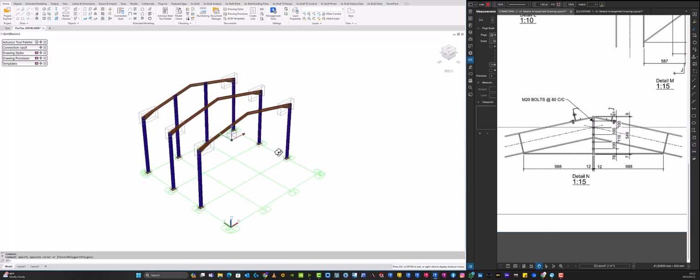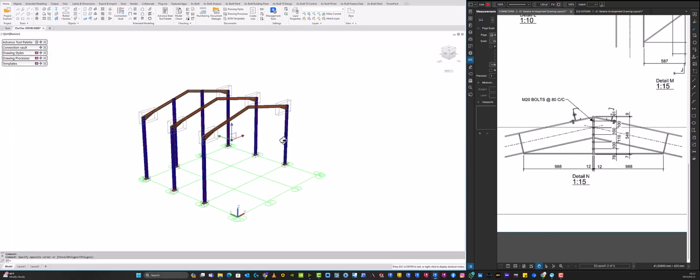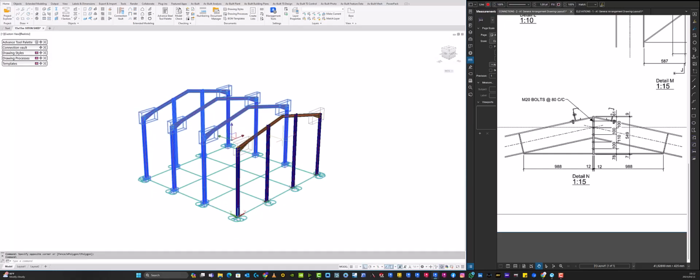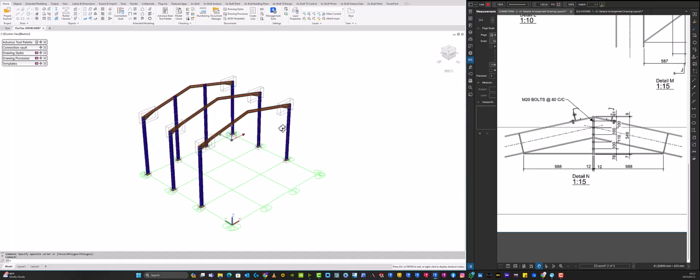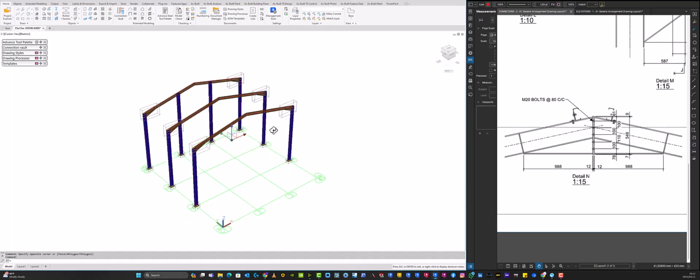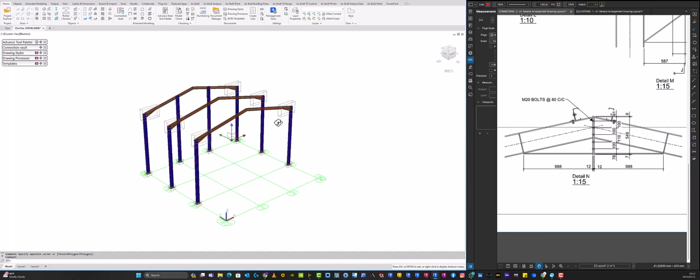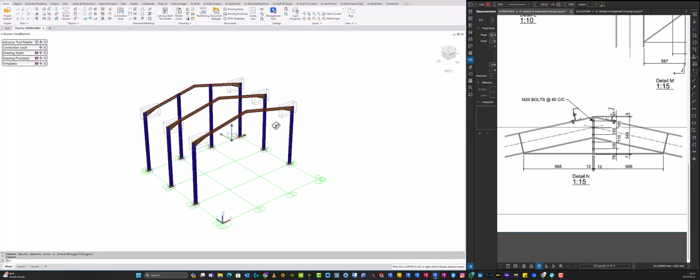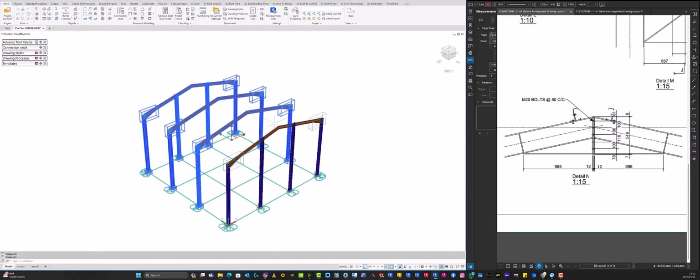After you have done that, as you can see, if you orbit, and by orbiting you press shift and the center button of your mouse, it is going to show and orbit only the objects that you have selected. From there, you go to Advanced Steel 2 palette, click the drop down arrow, and then come to the second button from the bottom.